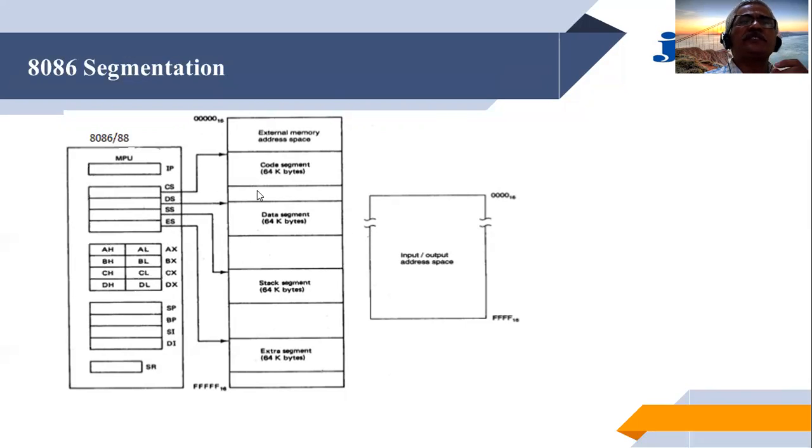But when you peek inside the 8086 and look at the registers, the purpose of a register is not only to store intermediate results. Some of the registers also store the address of the memory; they are the pointer, index or base registers. But the size of each register, as we know, is only 16 bits, while the address is 20 bits. So with only one 16-bit register, we can only take care of 64 kilobytes of addresses.